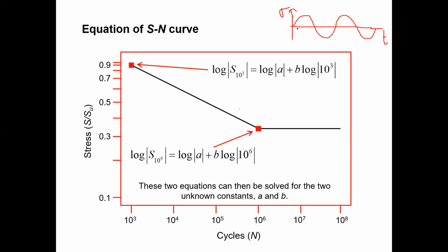I understand the same stress, but if we're not changing the stress, why is the y value decreasing? Because, if you remember the earlier slide, they explained crack nucleation. With the number of cycles inside the material, cracks will be initiated because the material is not perfect.